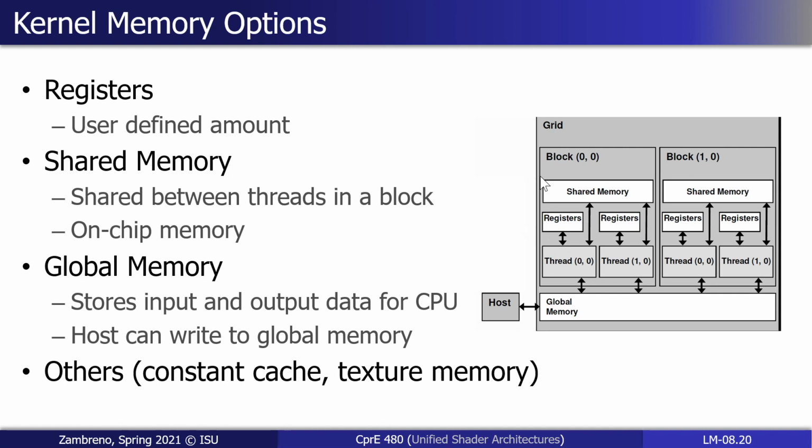Then what there is, which is different, is for these individual SMs. This is showing it from a kernel's perspective, but also it has the architectural implication is very similar. There's also just a dedicated region of shared memory. And that is a separate block of memory of software allocated memory versus cache, which is this hardware managed memory. You can refer to it as scratchpad as a term that we see used in the embedded system context, but in the GPU context, we just see it referred to as shared memory, which is allowing us relatively straightforward and cheap synchronization amongst threads that are inside a single block here.